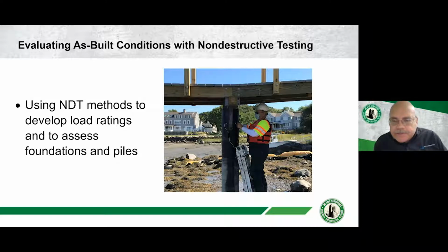So we've got a series of sensors ratcheted to the top of the pile, and I'm about to impact it with a hammer, and the energy waves will propagate down through the pile, kind of like a waveguide, and those energy waves will be reflected off the tip of the pile and come back up to the surface. We have the velocity of the energy wave. We have the time it took to go down and back. Very easy calculation to calculate the length of the pile.